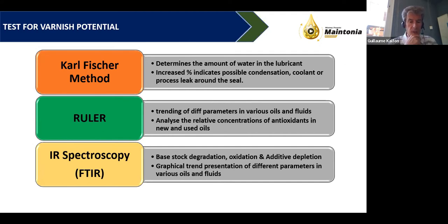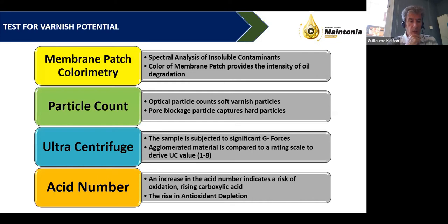I will still add a few comments on the previous slide. So particle count can be a sign of varnish, especially the very small in the ISO 4406, which has 3 categories. The very small category size, if that is erratic, going up and down, unstable, can be a sign of varnish. So it would be a complement of information.